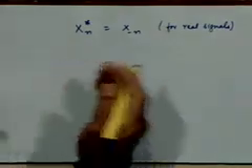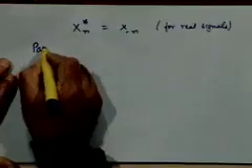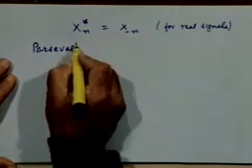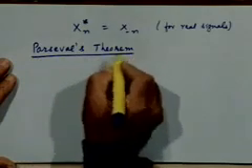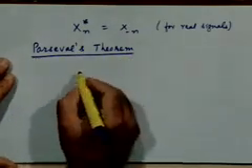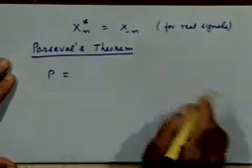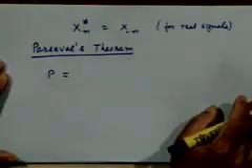There are many properties of Fourier series, but since they are very similar to the properties of the Fourier transform, which I am coming to shortly, I will not discuss all of them. They are parallel to each other, right? So if you know some of the properties of the Fourier transform, you also know the corresponding properties of the Fourier series. But one property which I would like to discuss here very briefly is Parseval's theorem. Do you remember that? It's a very important result because it relates the energy calculation of the signal in the time domain, energy or power.